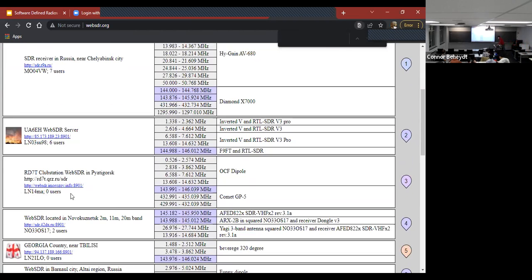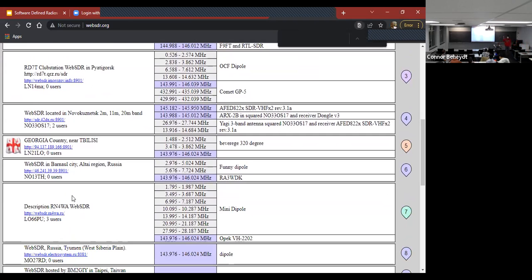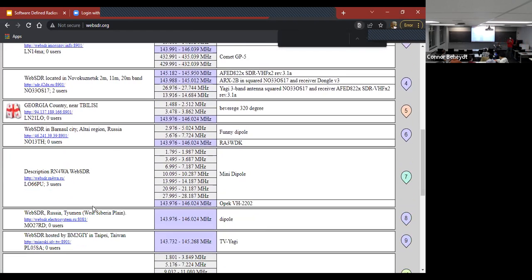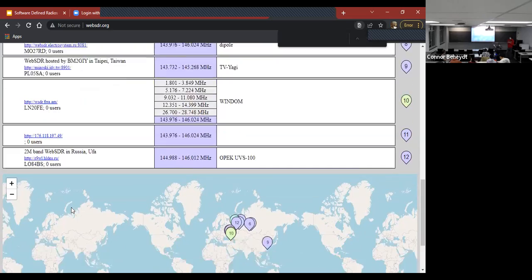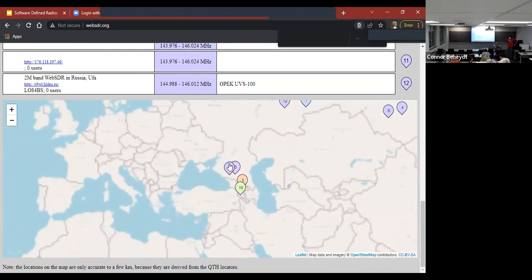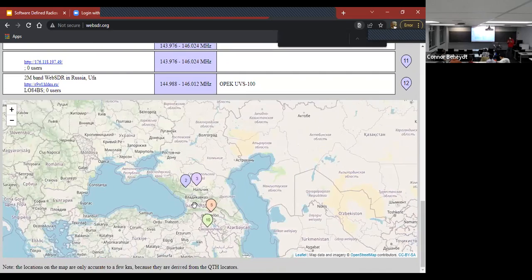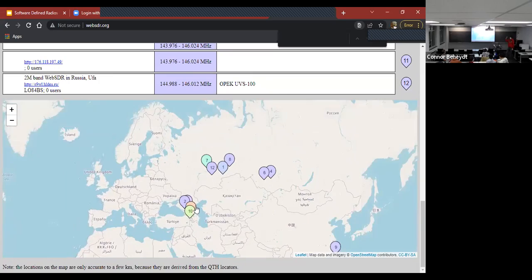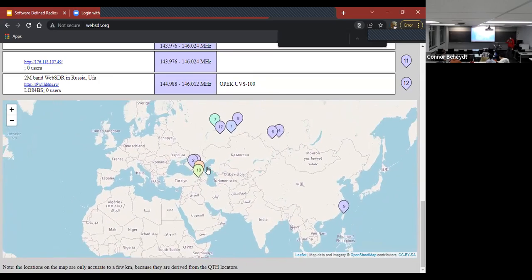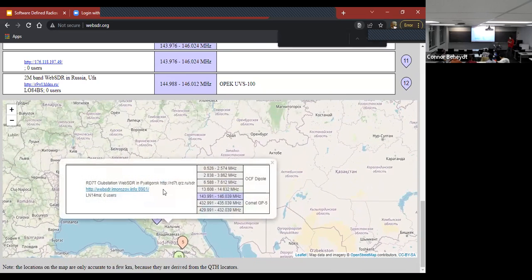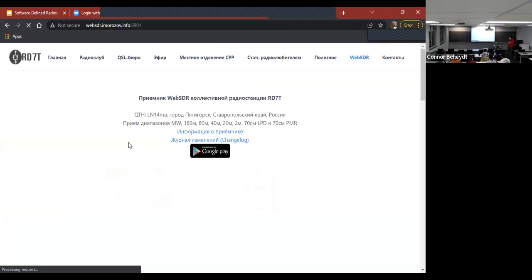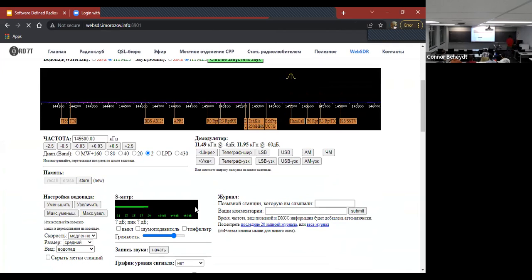The thing we were transmitting on the 433 signal was using 433 transmitters. We also have the receiver. This was last semester, right? So you can transmit and receive on 433 megahertz, I believe. So if you want your project to use some RF signals, you can use these transmitters. We have many of them as well as the receivers. Our next meeting, I'm going to borrow this.